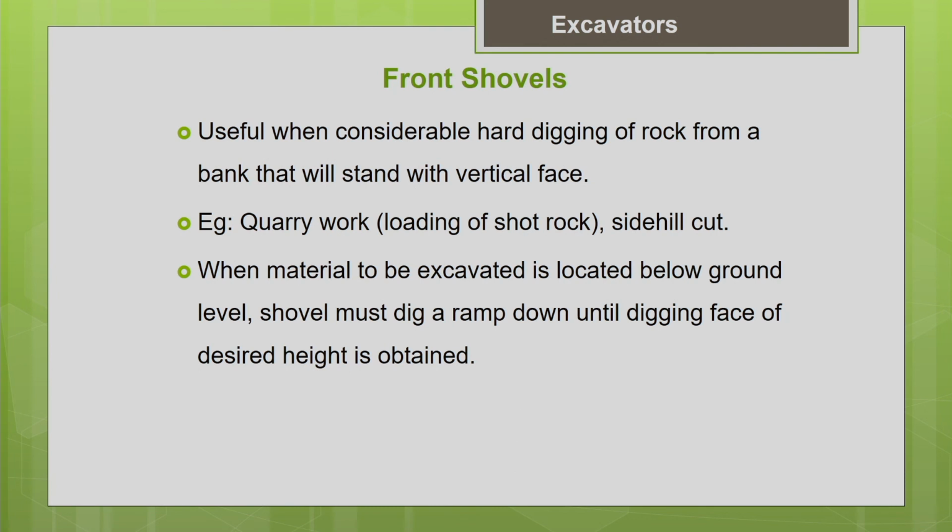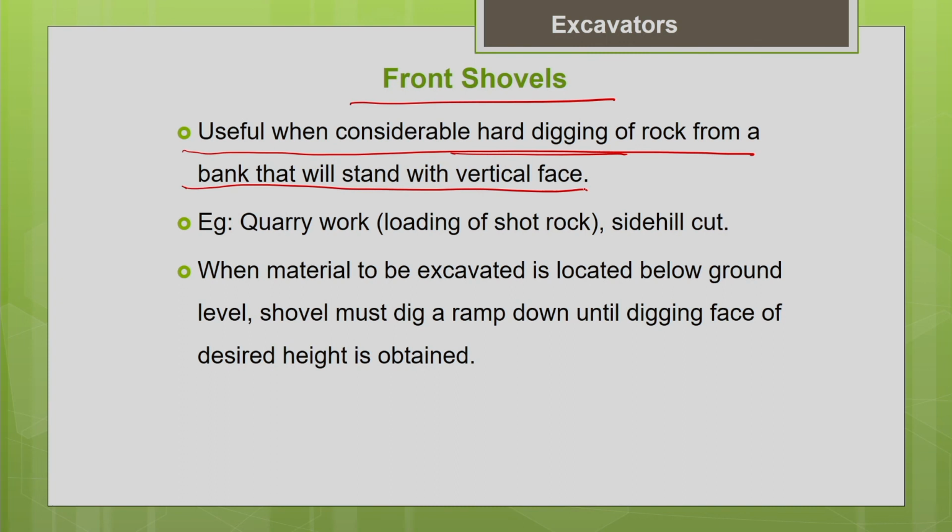As I told you, this front shovel is generally needed when you want hard digging of rock, at or above the ground level. You can handle the rock easily with this machine, so this machine is the right choice. It is useful when there is considerable hard digging of rock from a bank that will stand with a vertical face. That means this machine will give you very good productivity when it is used for excavating material which stands like a vertical wall, perpendicular to the ground. Say, for example, you are going for a hill cutting, which stands vertical. In that case, it will be very convenient to use a front shovel.